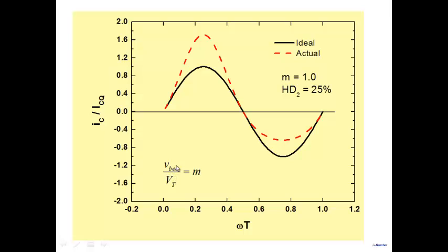And you know that output voltage is related to input voltage through gain. So how do you get a large output voltage? You will have to apply a large input voltage. And if you apply a large input voltage, what do you get? Larger distortion. Alright, so as you increase the output voltage swing, the distortion will keep on increasing. That's a natural consequence you cannot avoid because of the nature of the amplifier that we have.